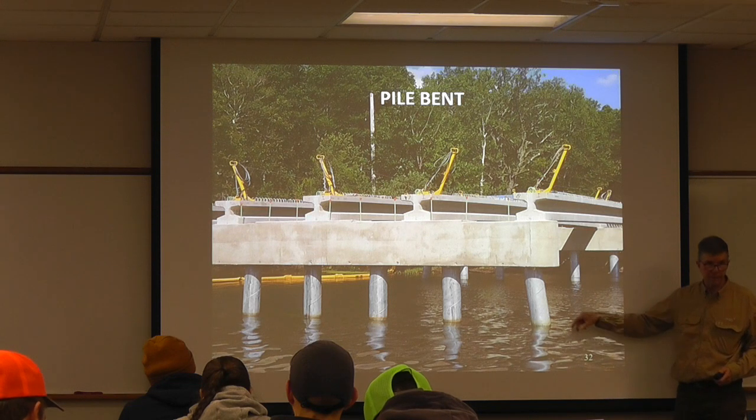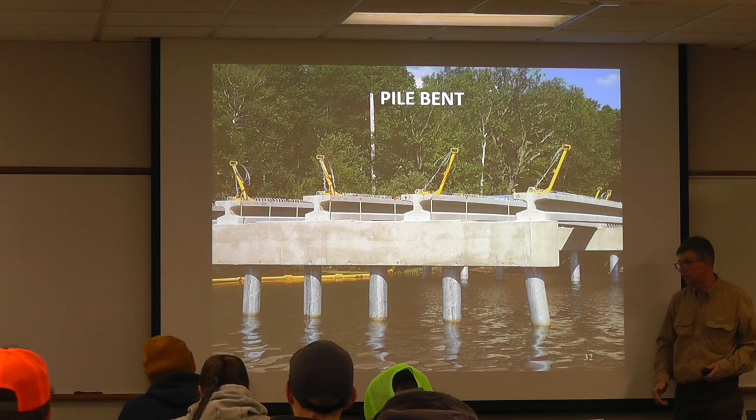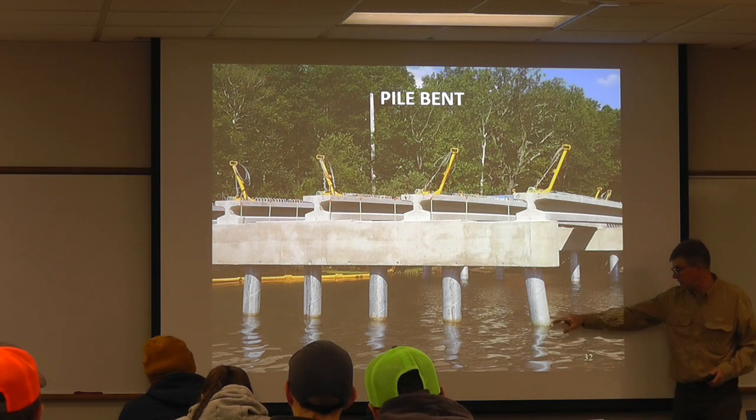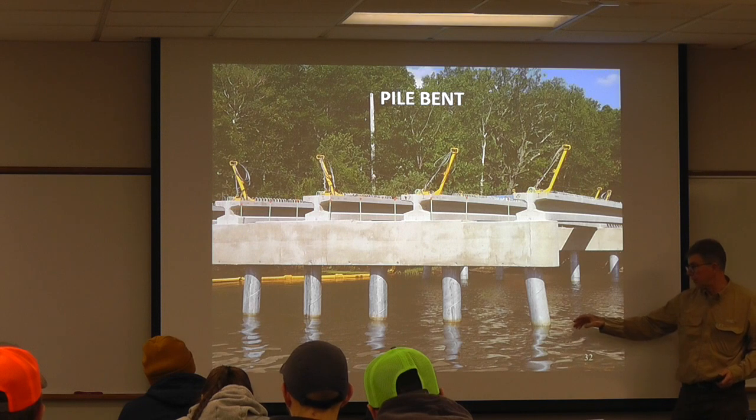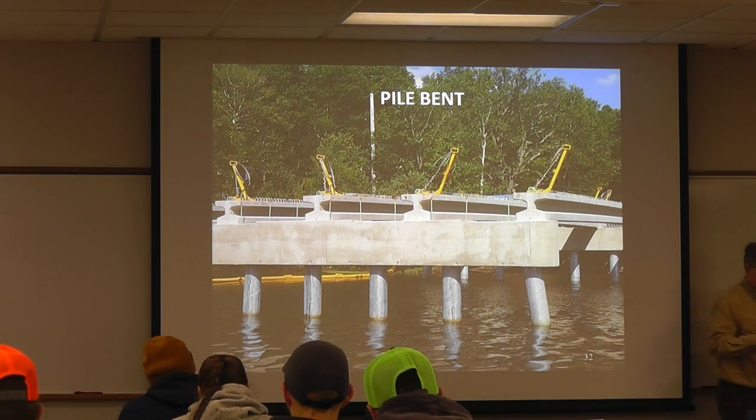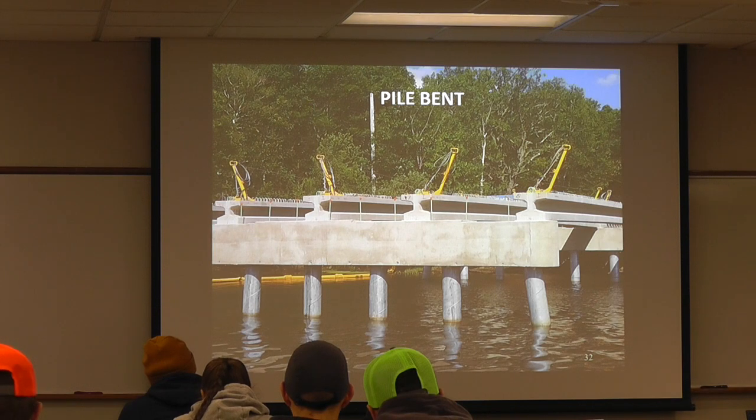So you'd end up with a big cofferdam and constructing a footing in the dry and whatnot. It's pretty expensive. So this way, you can do this method. Then once your piles are driven, instead of a true cofferdam, they could maybe do just a set of sheets, and it'd be cheaper than doing a pure cofferdam.